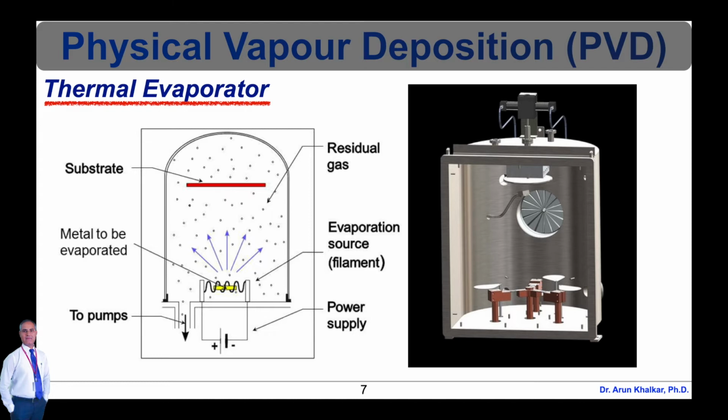In this process, the first important parameter is optimization. Purity of the film depends on the purity of the source material and the quality of the vacuum. Thickness of the film varies due to the geometry of the chamber. Collision with the residual gases aggravates non-uniformity of the thickness.